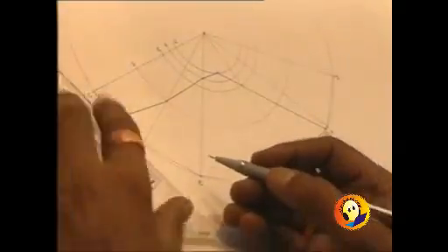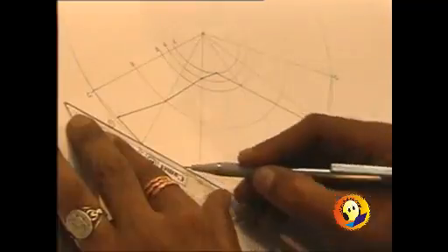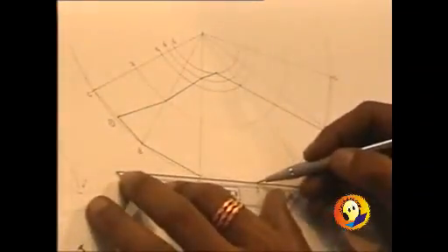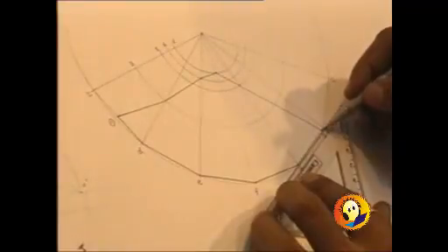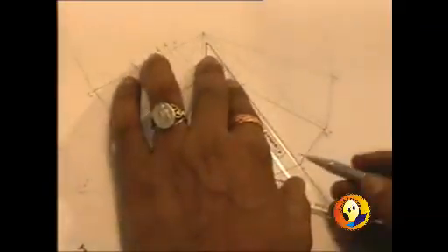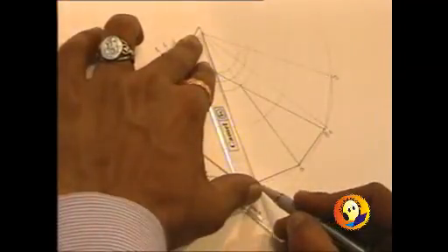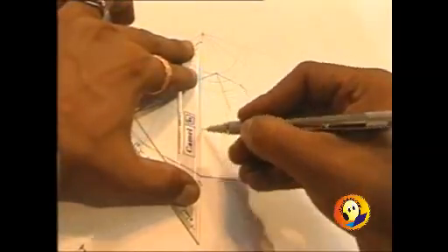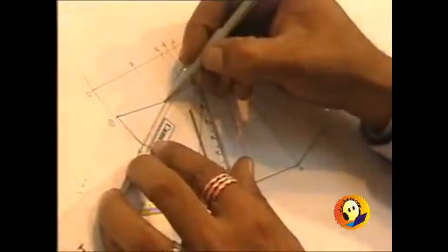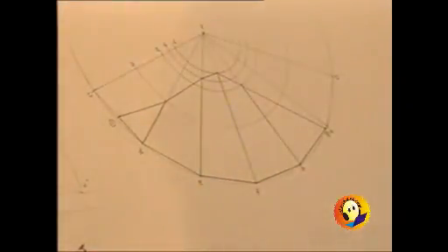let us darken the portion which is remaining, and so these sides of the base are intact, they are not removed, so they should be darkened, and the portions of the generators which are still present, even they should be darkened. The problem is important because the view that we have obtained did not contain the true length, and true length construction has to be done separately somewhere, and so we get the development of that hexagonal pyramid.